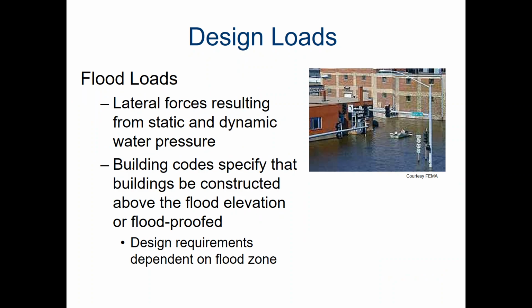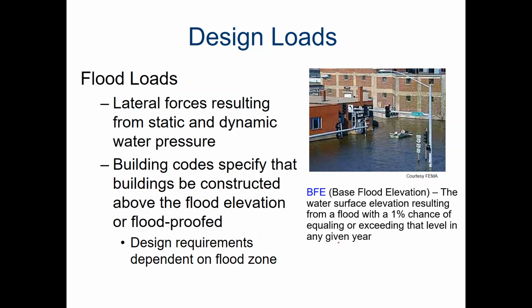Flood loads. Flood loads are something that hopefully we're not going to have to accommodate, but the important thing is that you build above the base flood elevation, which is the water surface elevation resulting from a flood with a 1% chance of equaling or exceeding that level in any given year. All right, so lateral force resulting from static and dynamic water pressure. Yeah, you're not supposed to build in flood zones.